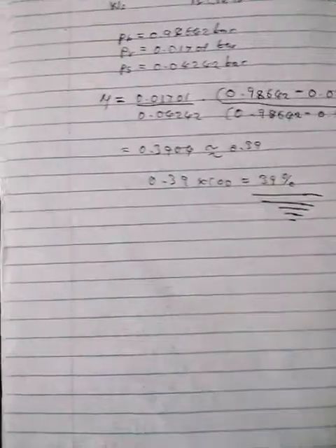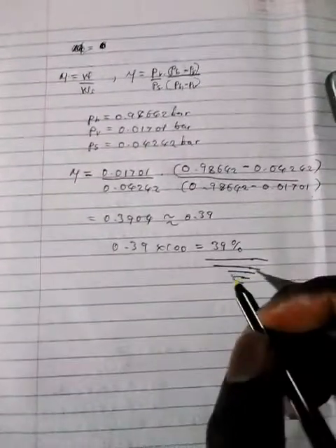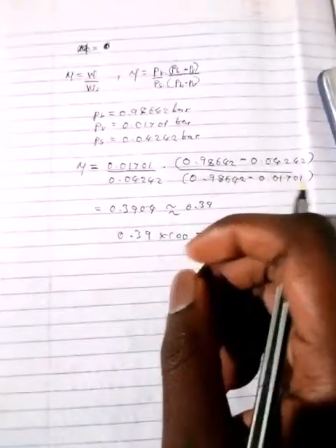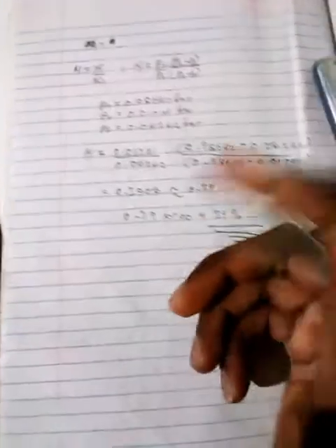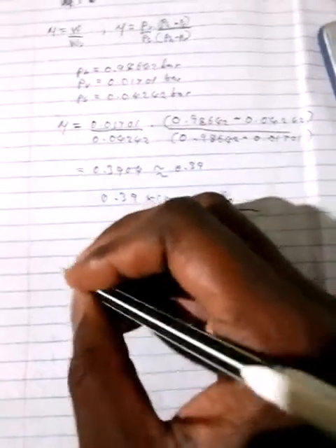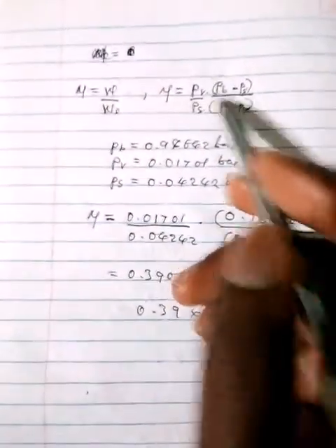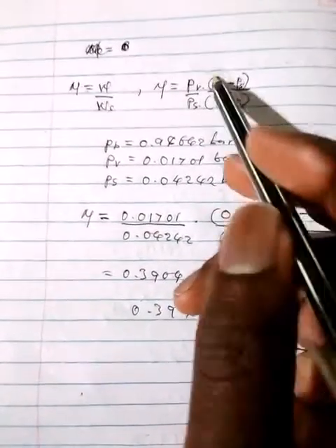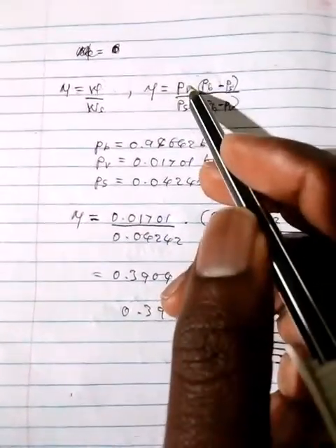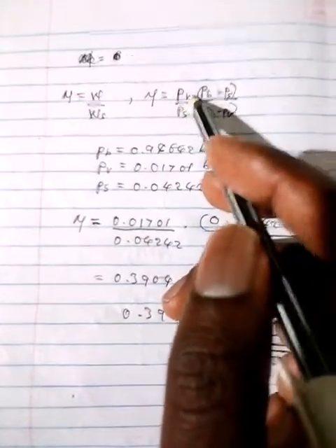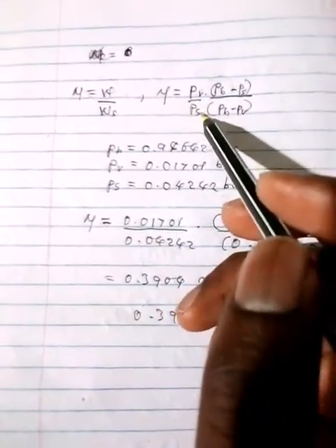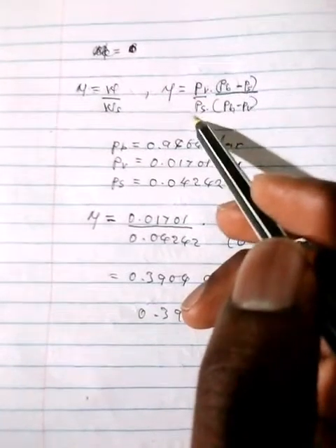So I think we'll end here for now. In the next one, we'll be looking at the next part, which has to do with finding the vapor density. But anyway, in conclusion, you have two ways of finding your degree of saturation. One makes use of the specific humidities, and another makes use of just the pressures given: the isobaric pressure, the partial pressure for the vapor, as well as its partial pressure at saturation. This is obtained from the steam table.